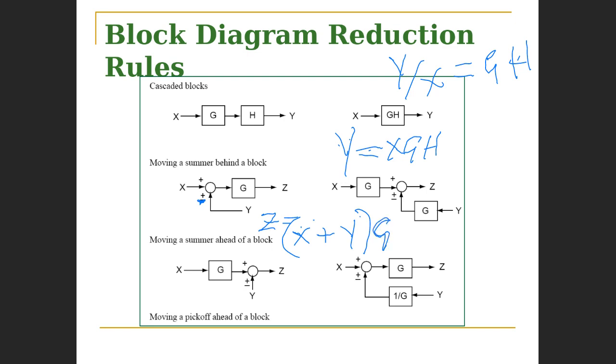Thanks again. So what we're seeing here is that we're taking this input. The input is actually X plus Y, and X plus Y is now fed into G, and the result is we simply multiply the input by the transfer function, and that's exactly what was done here. Now, what we need to appreciate is that whatever this system is doing, the equivalent, which is the one where we have removed the summing node from the input of G to the output of G, must be saying the same thing. Yes? And so we're going to now examine to see if that's the case.